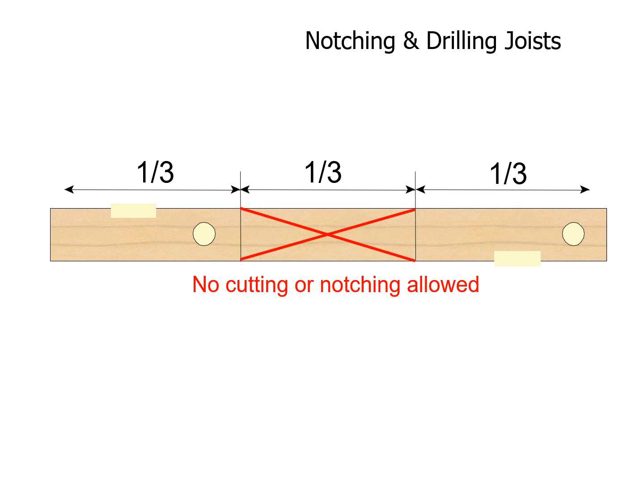This is just going over telling us to be careful when we're notching and drilling our joists and studs. Now, keep in mind our joists: we always leave the center third section alone. It's something I learned day one in construction. Hey, if you have to notch or drill the ends it's okay, but leave the center alone.